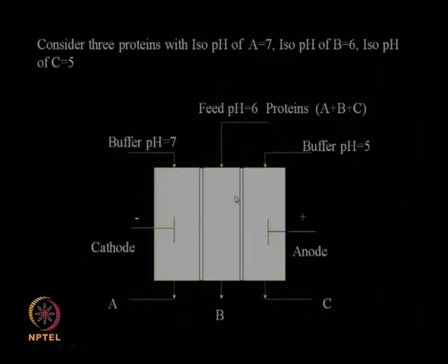So the separating chambers are made up of membranes. Okay, so these membranes will allow these proteins to migrate towards its isoelectric pH. Okay. So this is another way of separating out proteins having different isoelectric pH actually. But this is not a very popular type of large scale separation process, but it can be used on a small scale in laboratory settings. But the main principle here is based on isoelectric pH.